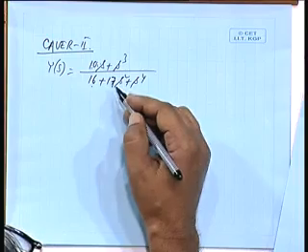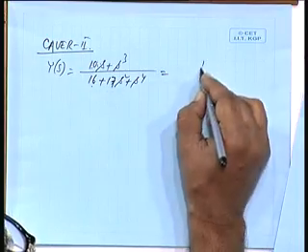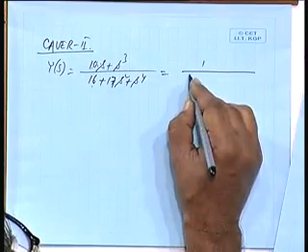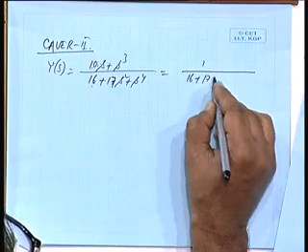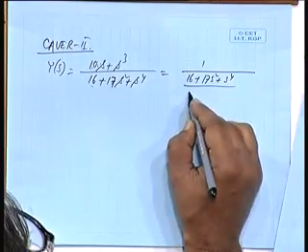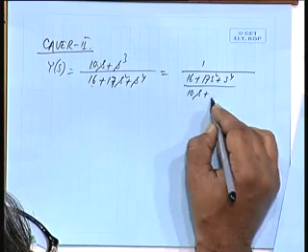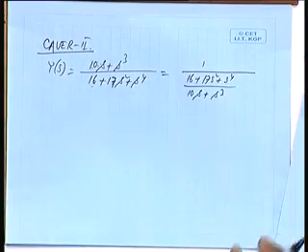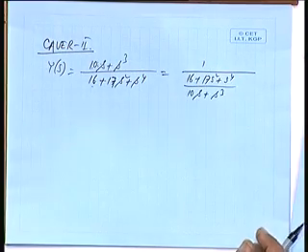So, obviously, this will fail. So, I will write this as 1 by Y, that is (16 plus 17s squared plus s to the power 4) divided by (10s plus s cubed), and now carry out the division with quotient as 1 by s and its multiple. Is that okay? So, you will get Foster 2.